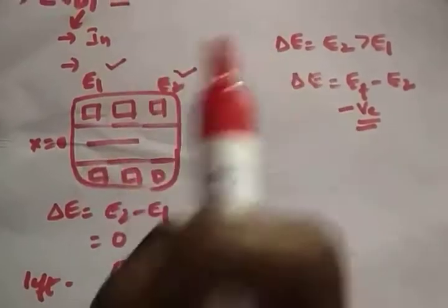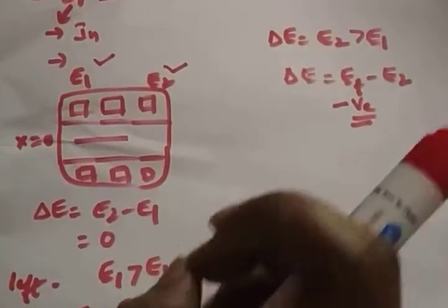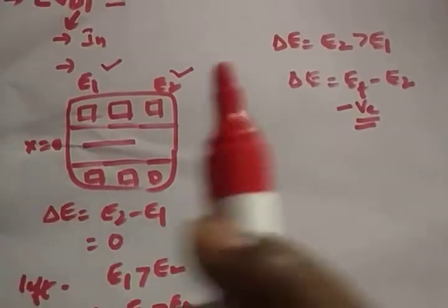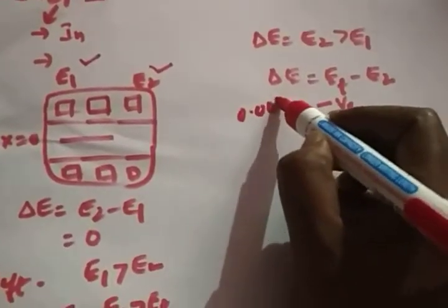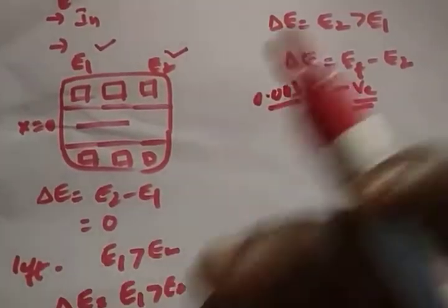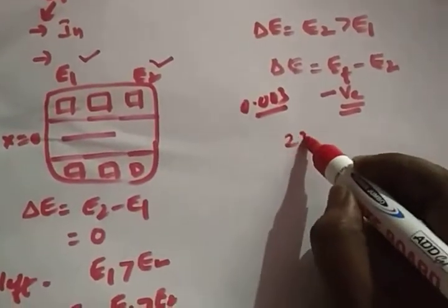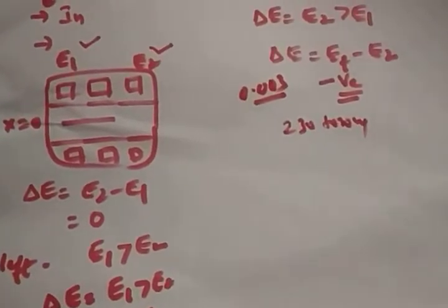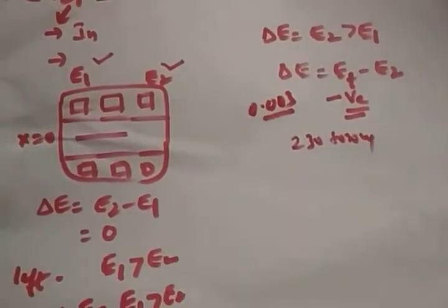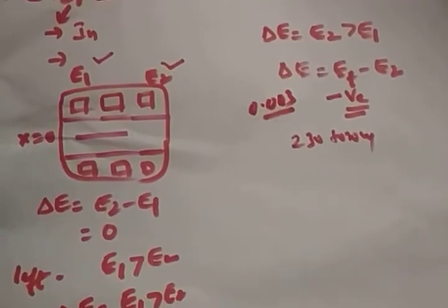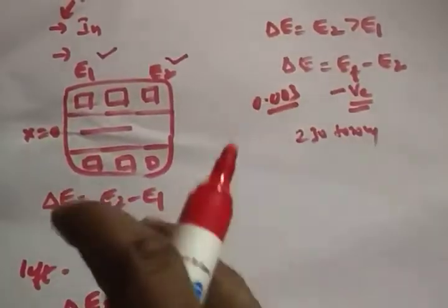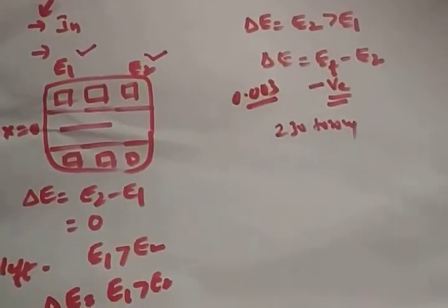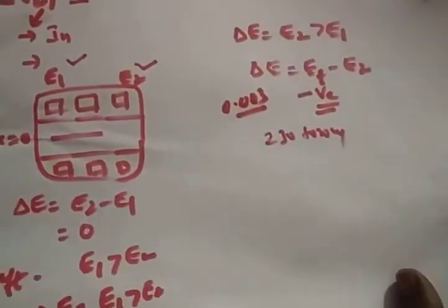After that, what are the advantages? Definitely it can be used to find small changes in displacement, the smallest change up to 0.003 also. It can also be used for large displacements, 230 to 300 mm of displacement, with this type of LVDT. There is steel protection against electrical shocks, and rugged construction. These are the things that we discussed in our last session.